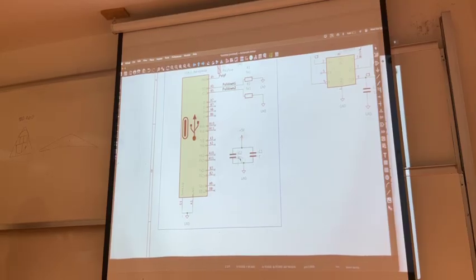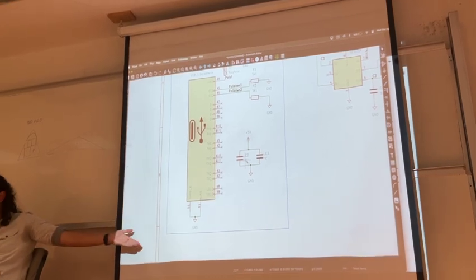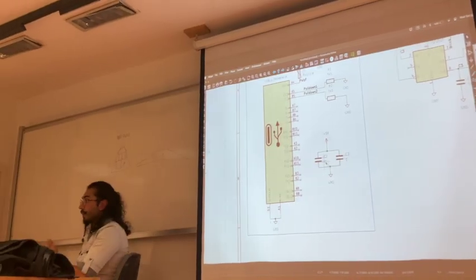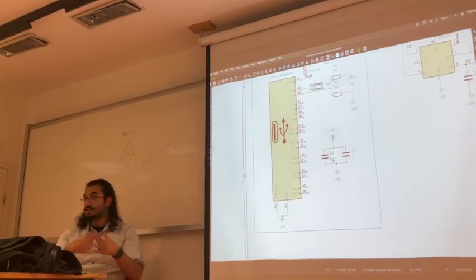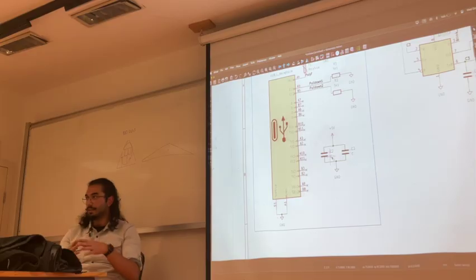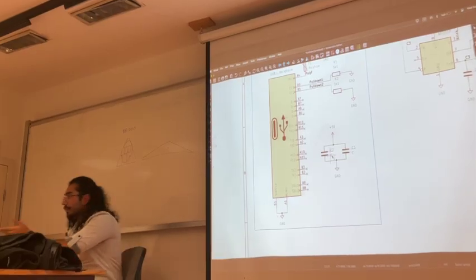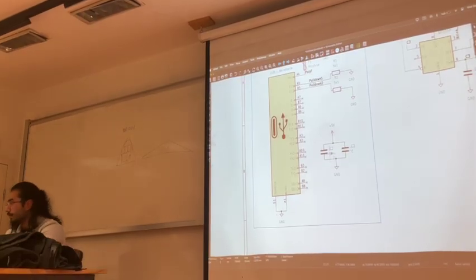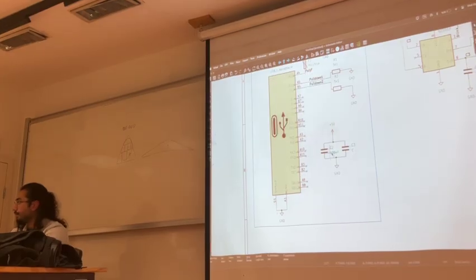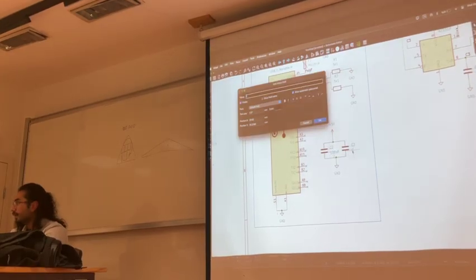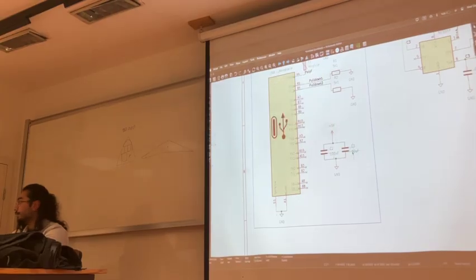So I connect the decoupling capacitors across the power rails, which is 5 volts and ground in this case, and I put the decoupling capacitors really close to the ICs when I do the layout. That is the reason they're separate from when they're here. They are the decoupling capacitors. I am going to set one of them to 100 microfarads and 10 microfarads like we calculated before.